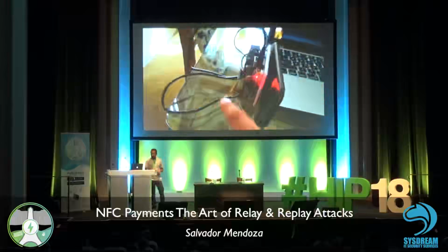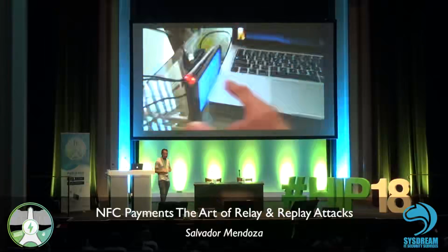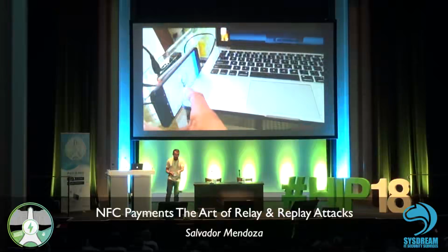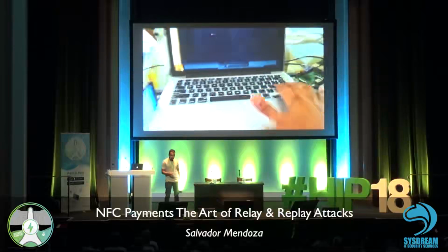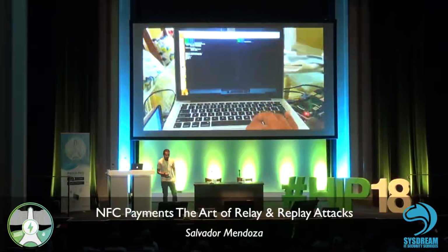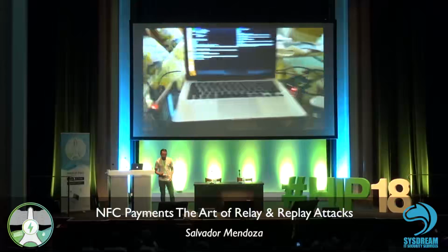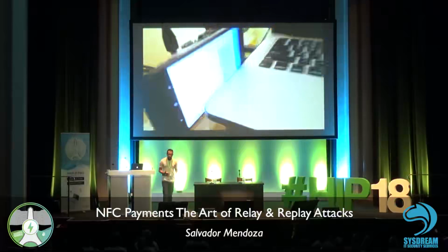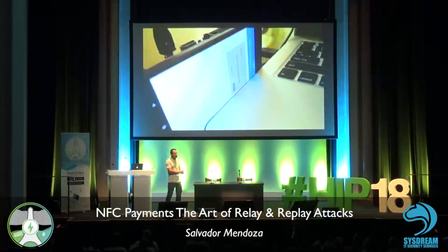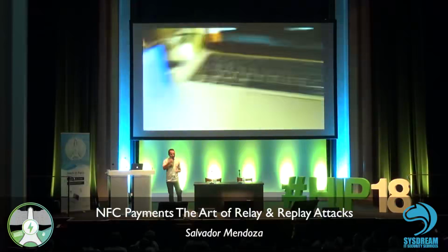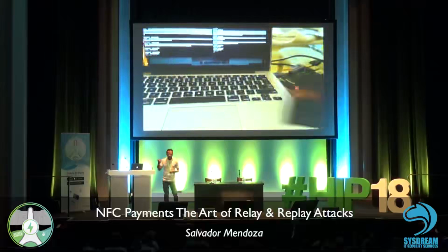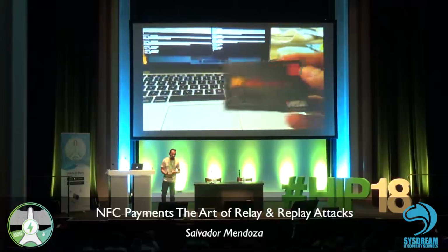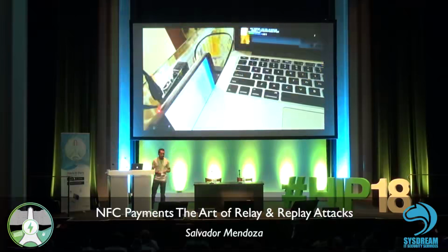And I have another Raspberry Pi, which is going to behave as the POS. I'm going to extract the data from the chip and PIN card. Basically, I got the card sending NFC commands, sending back to the SDR and to another USB device, and reading the chip that way, implementing the APDUs over NFC.